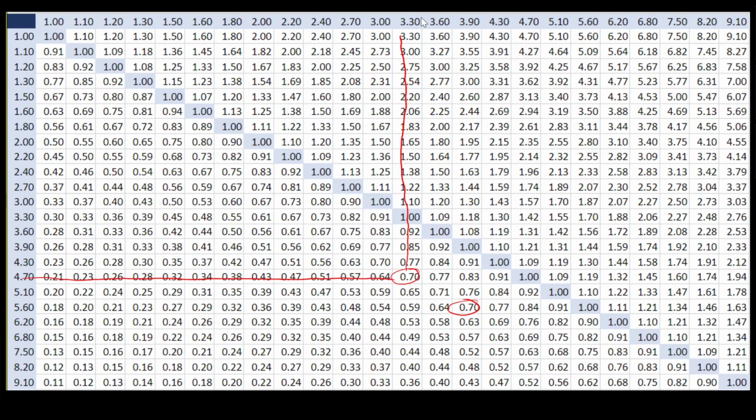Suppose we let our feedback resistor be 330K and our input resistor be 47K. We would have a gain of 7.02, which isn't too far off from our desired. Let's try the other pair. Here, let the feedback resistor be 390K and divide that by 56K. We end up with 6.94. Given the two choices, it looks like 7.02 is a bit closer.